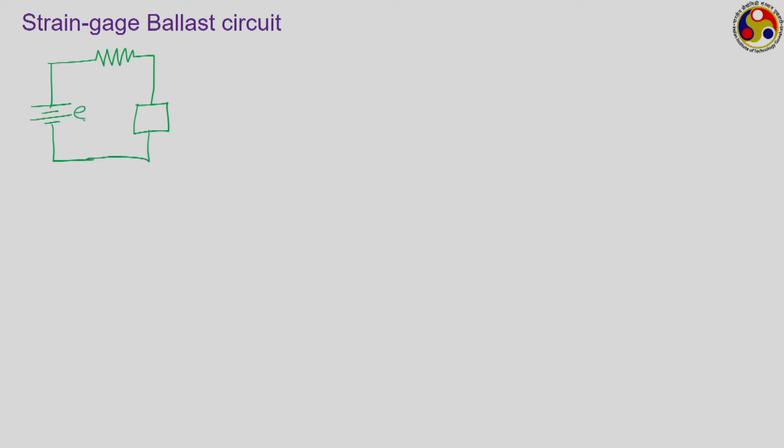Let us say this voltage is Ex, R is the gauge resistance, and Rb is this ballast resistor, and then across this you will be measuring this output voltage E naught. Mind you, here we are not at all talking about the loading effect, which will come in when we mount some kind of voltage measuring instrument here. Here we want to check the sensitivity of this particular circuit.